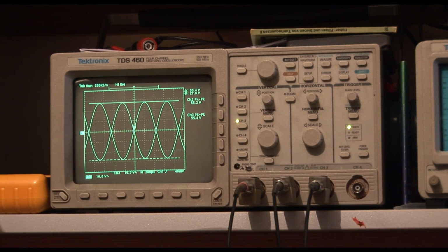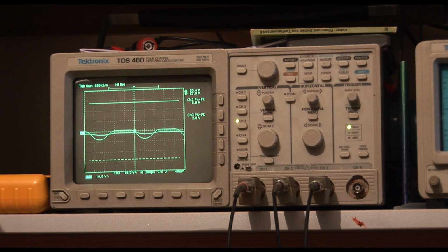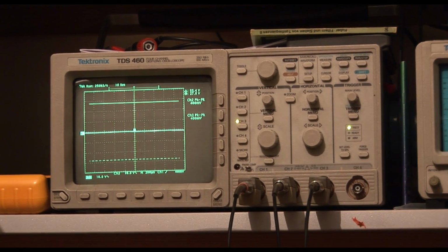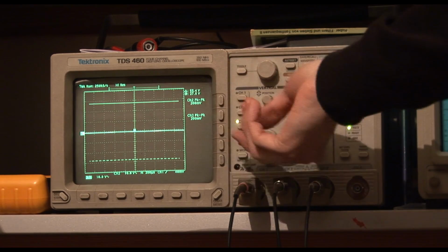And now let us measure the common mode gain. So first of all, of course, I turn it off again, and then I connect it in the common mode, and now I turn it on again. So now both signals have the same input. So here you can see the output if the input is common mode. And let me zoom in a bit because it's very low.